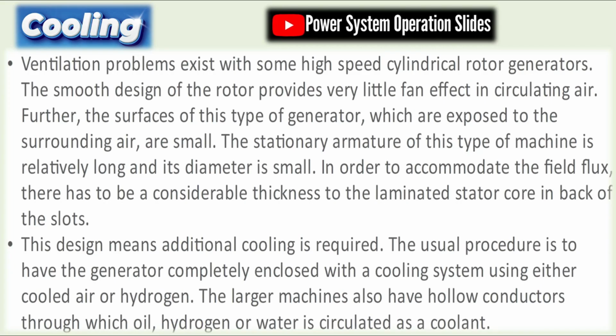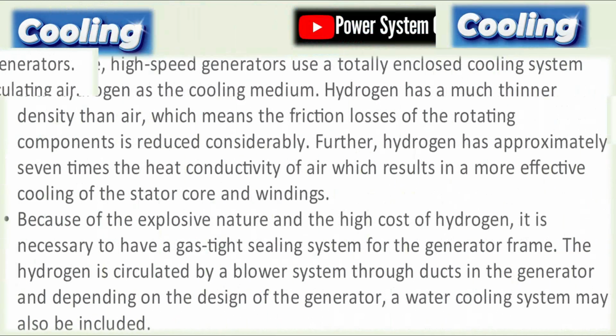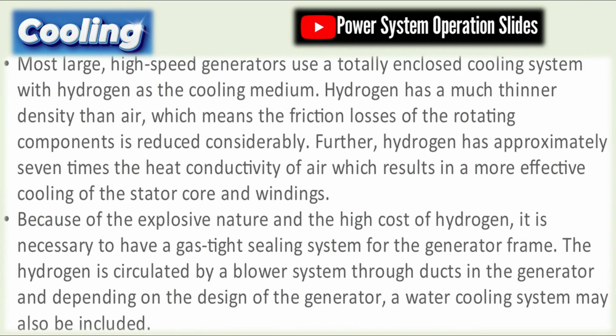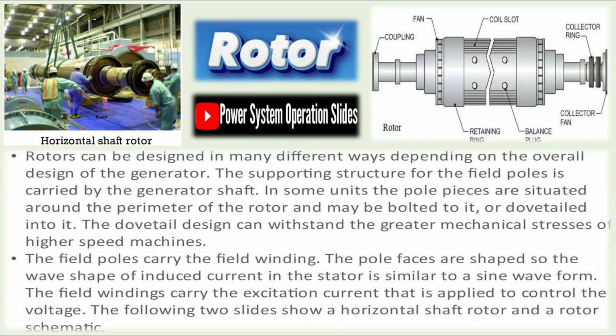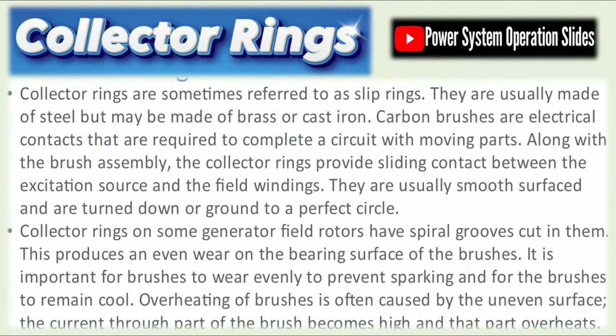Hydropower generation. Hydroelectric plants use dams to create reservoirs, controlling the release of water to generate electricity. The plant consists of intake structures, penstocks, turbines, generators, and tail races. Control gates regulate flow, and surge tanks mitigate water hammer effects. Francis turbines are used for medium head and flow. Pelton turbines are for high head, low flow sites. Kaplan turbines are adjustable and suited for low head, high flow rivers.